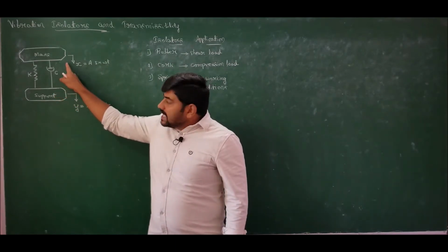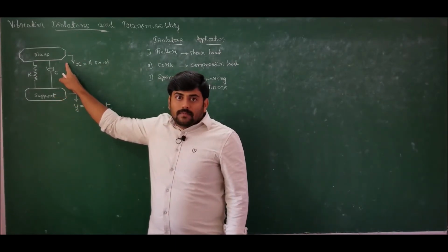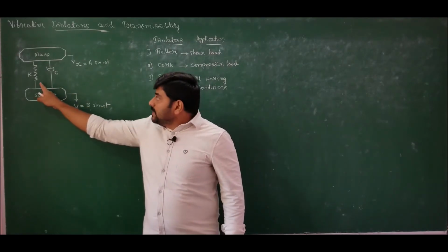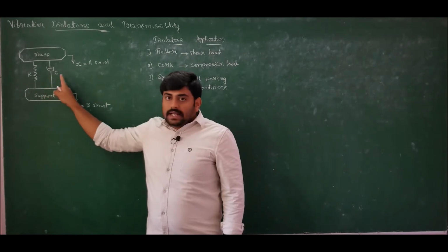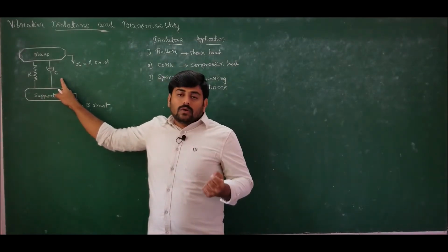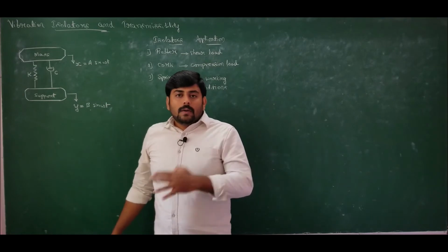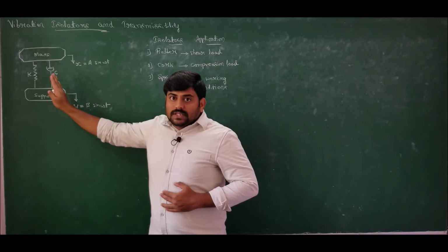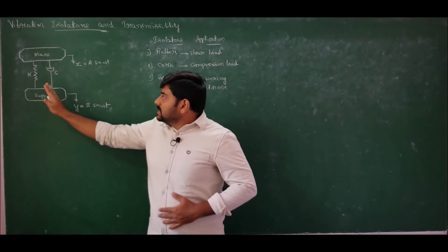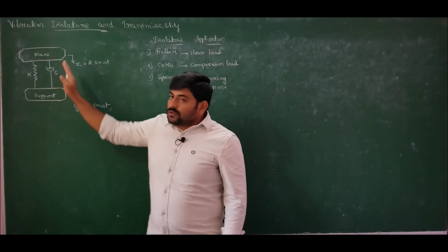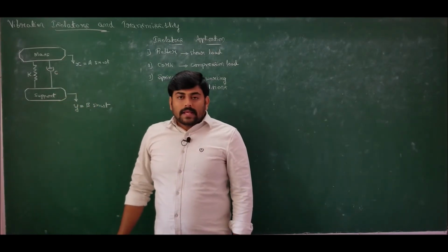So the force transmitted from the vibrating body to the foundation is through the spring and damper, because the spring and damper will absorb some amount of motion or force and allow only a fraction of the remainder to pass through them. Therefore the force which is transmitted to the base is nothing but the spring force and the damping force. The inertia force will not be transmitted to the base.